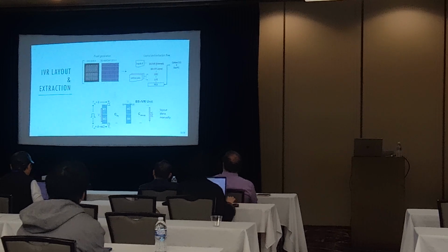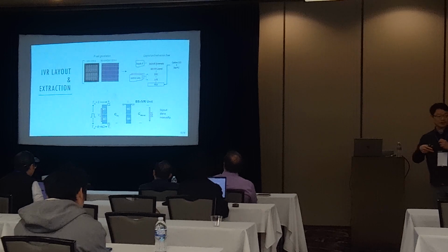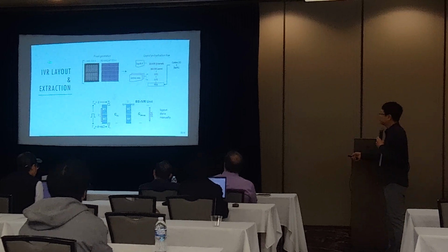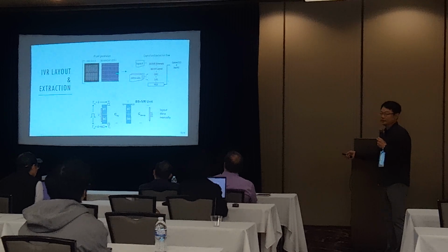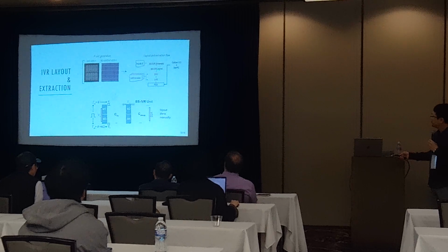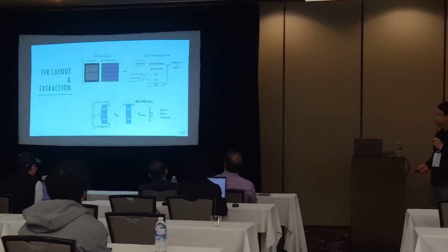And once you're happy with your schematic and your decisions, we're going to start doing the layout. First of all, we created key cells, tried them, put them in the library, and then changed them based on our sizing changes. We created key cells for the transistor, then the capacitor. Then, based on the schematic and the key cells, we start doing the layout, and we're going to make sure that it passes through DRC and LVS, and we're going to do simulation.